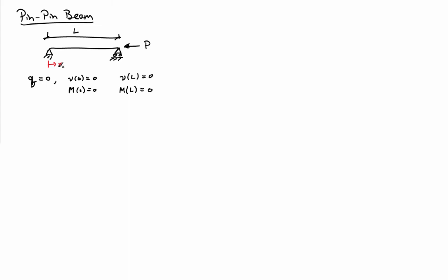So that's the setup here, and I want to look now at the solutions to the equilibrium equation. So my equilibrium equation in this case looks as follows. There's no q in my system. And I'm going to have to solve this using classical techniques of ordinary differential equations. Because I have two terms here, if I didn't have this second term, I could just integrate this 4 times. But because of this second term, I'm not able to integrate in such a simple fashion. I actually have to solve the differential equation using classical methods.